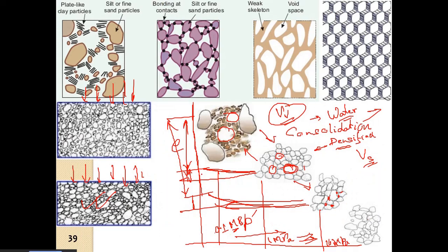So that is the most important part. In all of these plots which I have done, consolidation of the soil takes place only when the effective stress within the soil changes. So kindly keep that in mind, and that will happen only when we allow drainage from the soil. So the pore volume has to reduce.